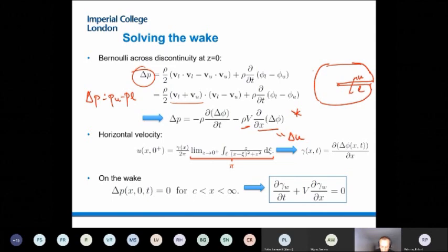Second, this depends on u, but now u can be written because it's driven by the presence of this distribution of singularities. So when we go very close to the axis, we can actually compute the integral that defines the velocity in terms of gamma. And as you get very, very close to gamma, the only effect that is retained is the local one, because that becomes a singularity, everything else goes away.